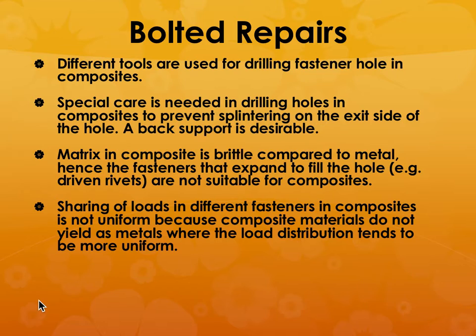And so when that is the case, you would put some kind of a back support so that the material doesn't spray out through the bottom and damage the material, damage the structure. And why? Because the matrix in the composite is brittle, especially when it is not hot, or after it has been cured, it is going to be brittle compared to the metal. So you try not to have some kind of a rivet, which is not a good thing for composites.